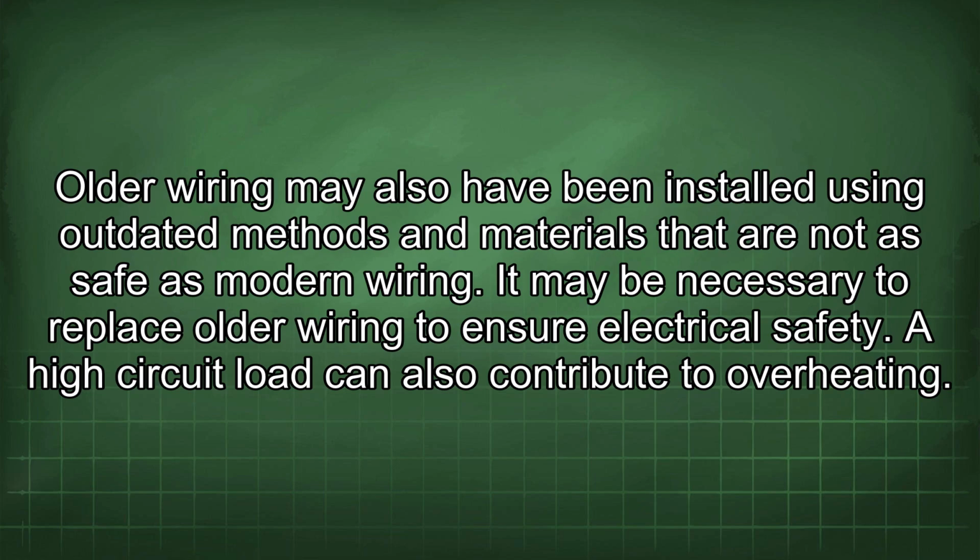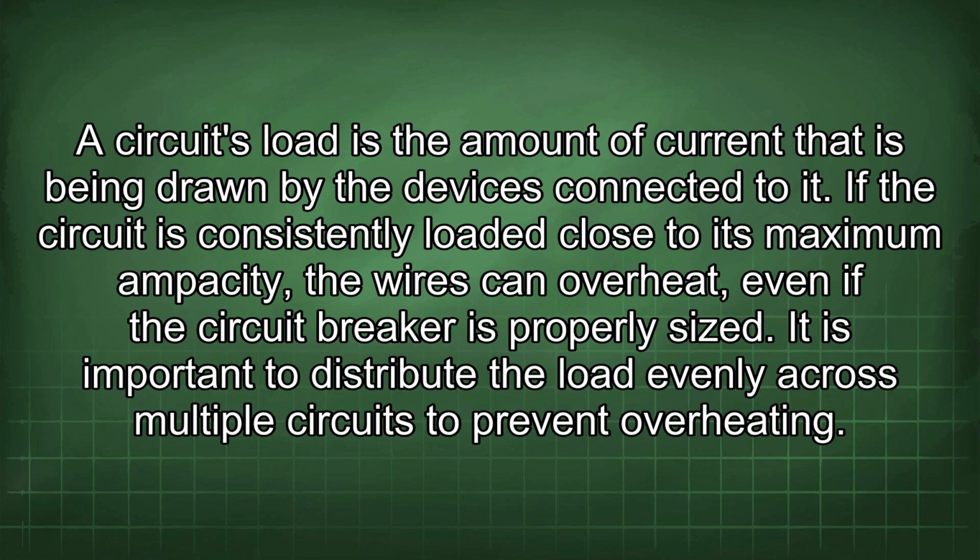A high circuit load can also contribute to overheating. A circuit's load is the amount of current that is being drawn by the devices connected to it. If the circuit is consistently loaded close to its maximum capacity, the wires can overheat, even if the circuit breaker is properly sized. It is important to distribute the load evenly across multiple circuits to prevent overheating.